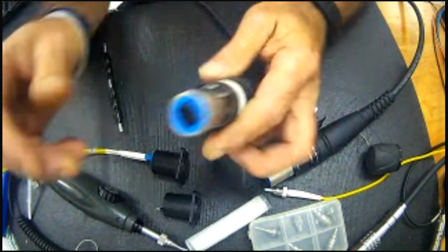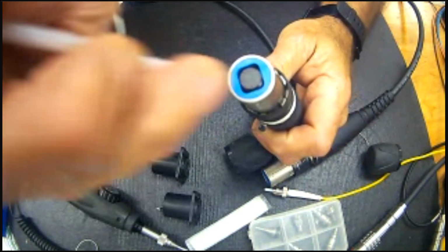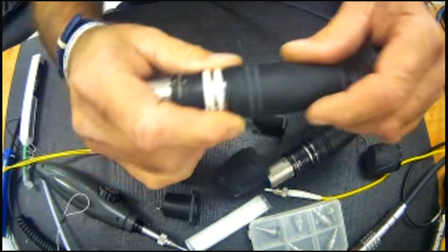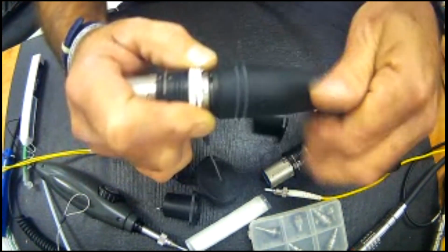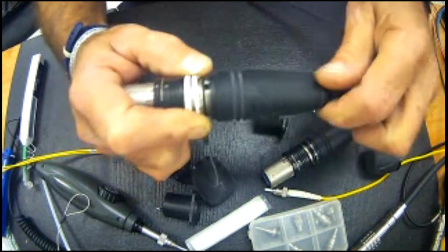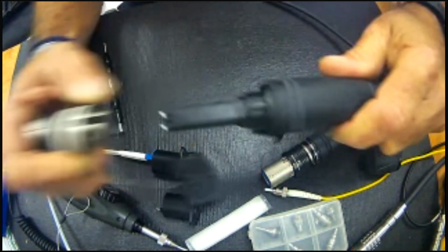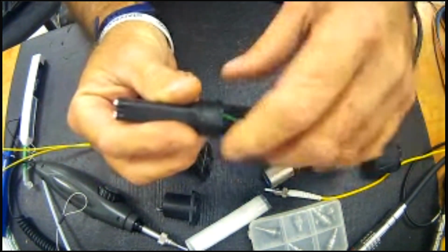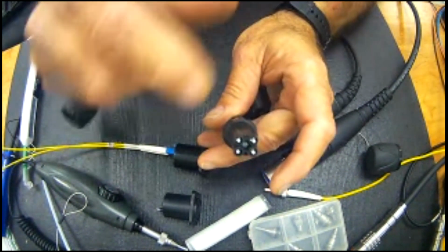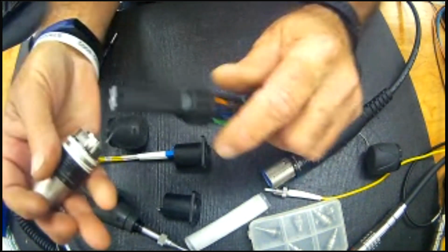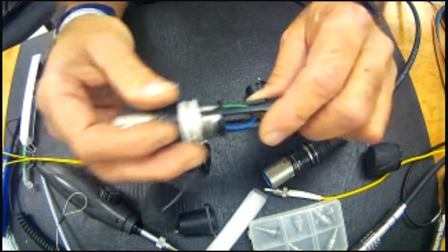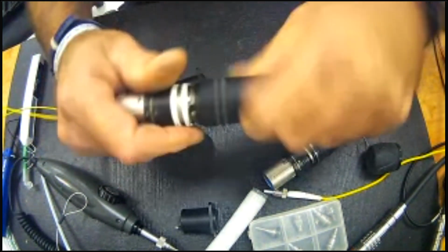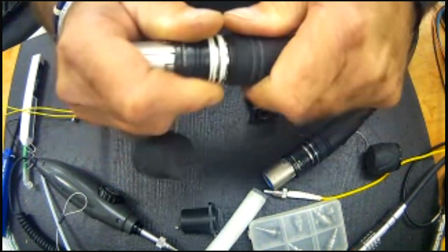So, in order to clean this baby, same way, you'd have to shutter it back. You'd have to own another fixture for the quad and work through it, or the exact same technique, just learn. And this is also a glass-only connector. So 4 pieces of glass inside. It's crimped and epoxied to attack 4. You can work those 4 contacts, visually inspect them, reassemble large notch, large way, bottom it out, move your back nut up, rotate it, snap, snap, snap. Beautiful.